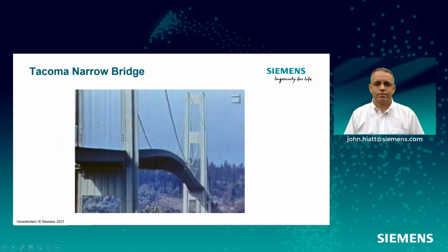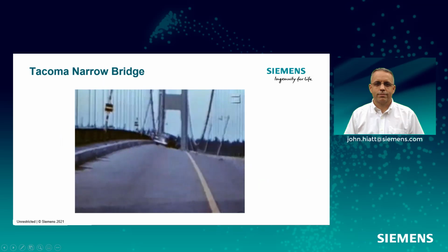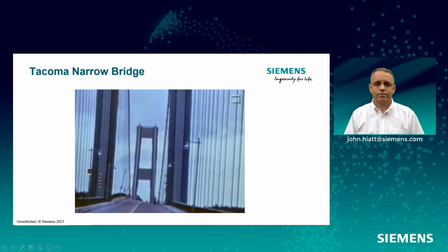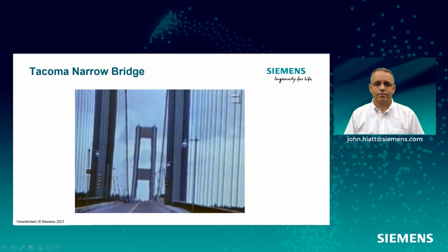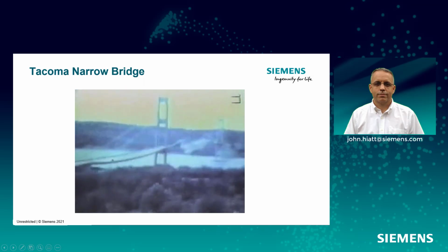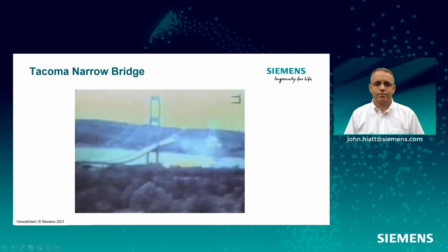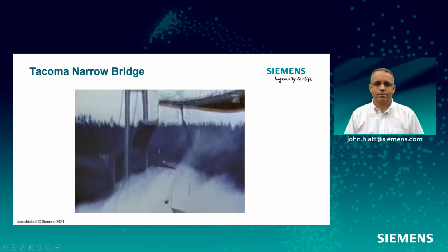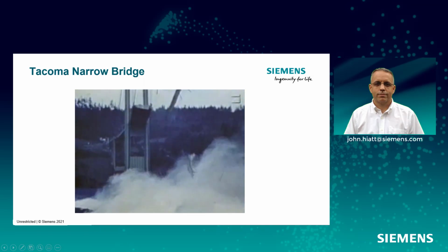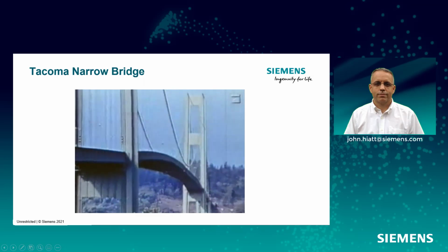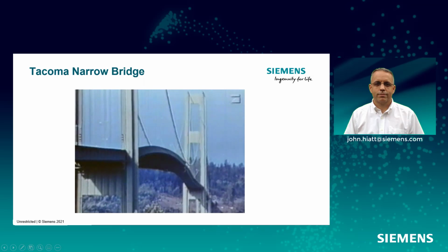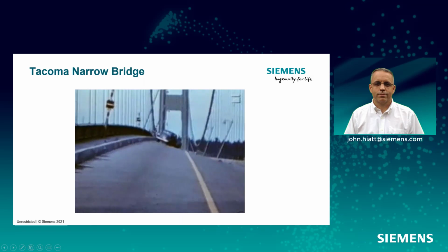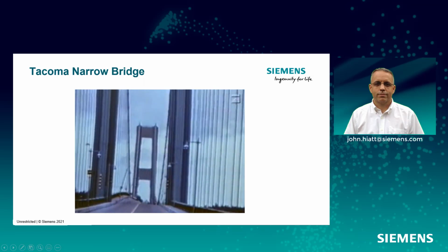Here's what we want to avoid, if at all possible. This is our favorite movie from high school physics. It's the Tacoma Narrows Bridge. Actually, this really isn't a fatigue problem, but it's a cool video. It's a forced response. The reason that bridge failed wasn't that it wasn't structurally sound, it's that they didn't anticipate the loading as the wind blew through those cables of the suspension bridge. Then it excited a resonance and it just got bigger and bigger and bigger. Any type of material or metal, if you put enough force on it, eventually breaks.